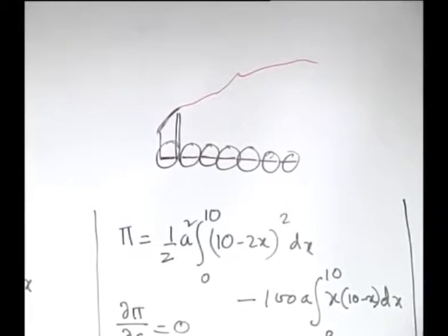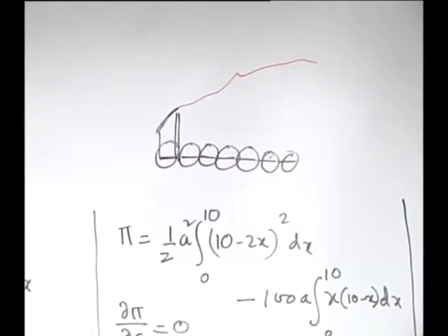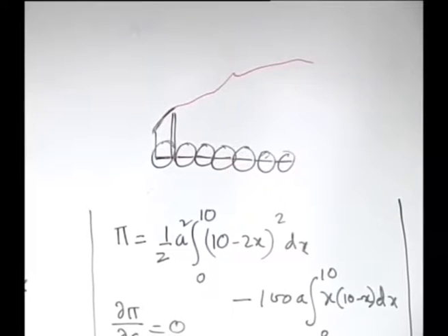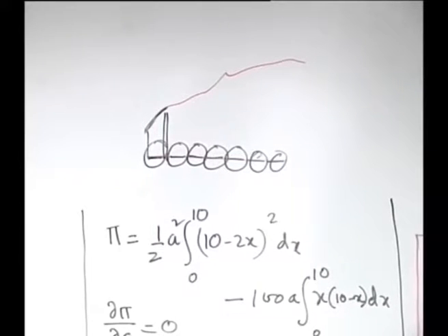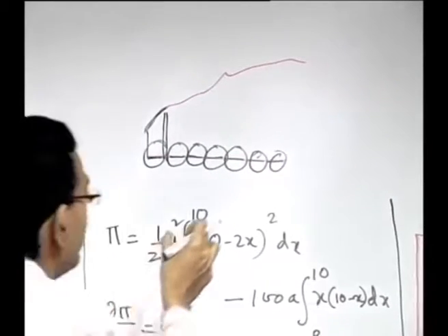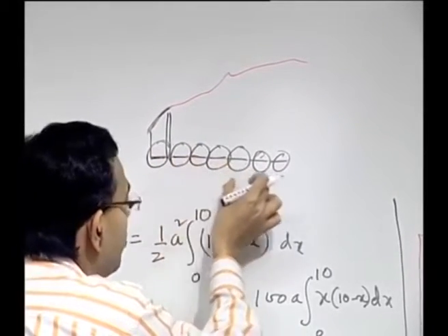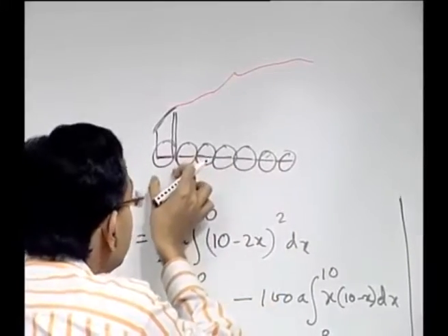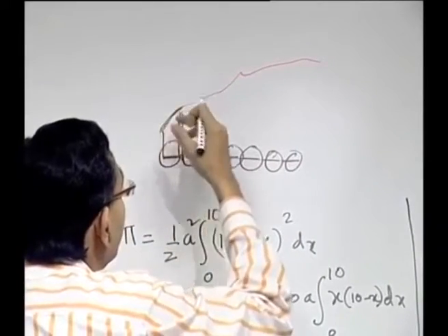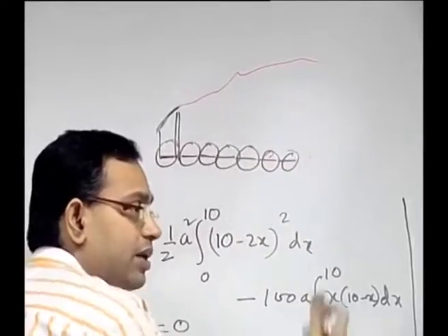So, you are reducing the requirement of the order of your polynomial function, but the cost that you have to pay now is that you are dividing your domain into a discrete number of subdomains, and for each subdomain you are going for a lower order polynomial to approximate your solution.